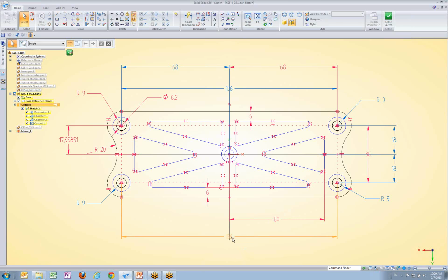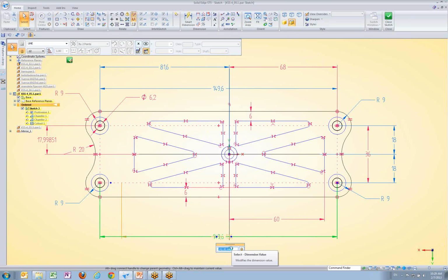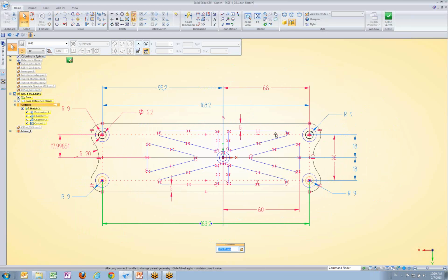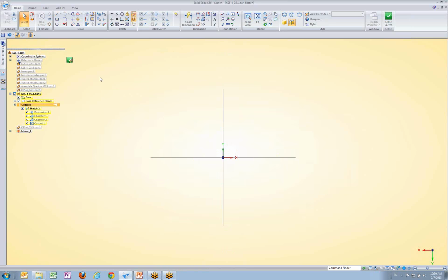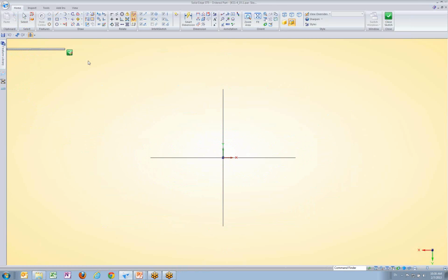Don't try this because you're going to make a mess of things, but if you find this dimension and say, well, this looks kind of promising, this might be able to do what I want, notice that because of how it's constructed, we're not adjusting the position of this cutout here. So this is going to be a real headache trying to reprogram the sketch to make the changes we want. I'm just going to go back to the undo all, which will bring us back to how the sketch was when I opened it. And let's just get out of here,